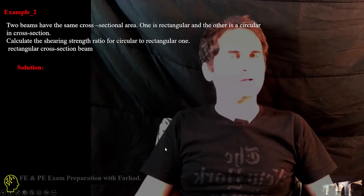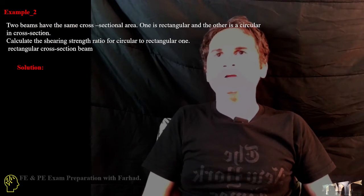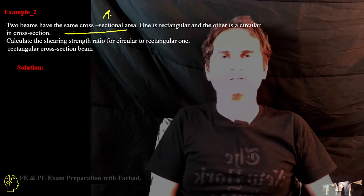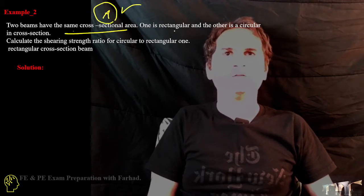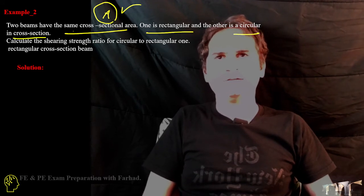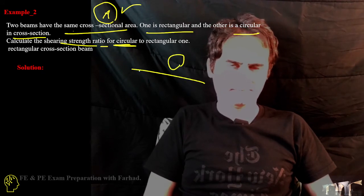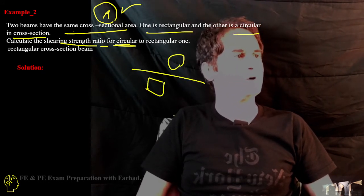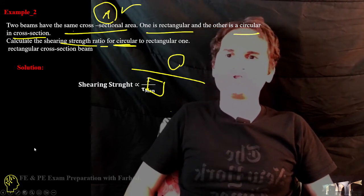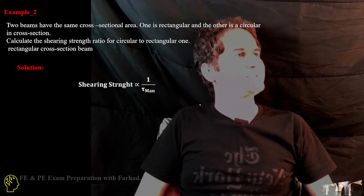Let's solve a different problem. In this problem, we have two beams that have the same cross-sectional area. So area is equal in both of them. One is a rectangle and the other one is a circular cross section. We want to calculate the shearing strength ratio of the circular shearing strength over the rectangular shearing strength. So let's solve the problem. Shearing strength again has a relation with inverse tau maximum.